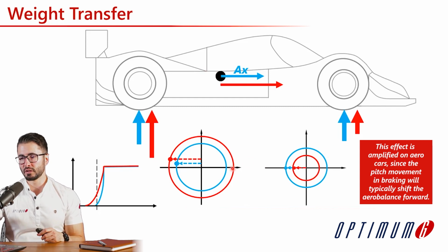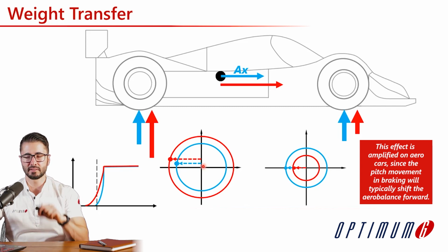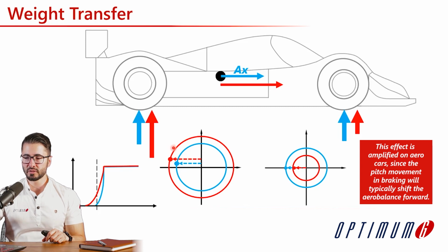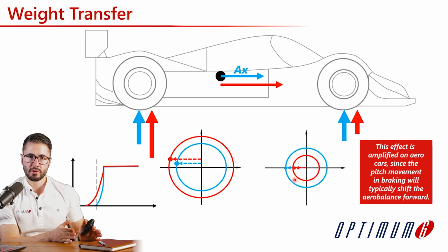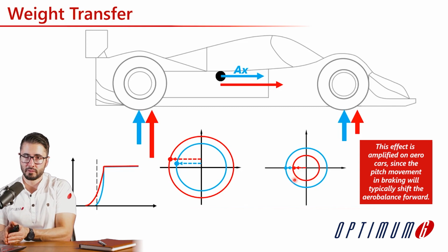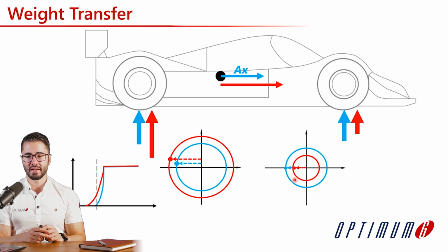So it's interesting to see that even though you are using more of the longitudinal force of the tire and slightly saturating it longitudinally, you still have higher lateral forces over here, while on the front you have lower lateral forces. If you increase the forces on the rear and decrease them on the front, you're getting a more understeering car. So here, as you apply the throttle, you're going to get more understeer, typically. So this is a corner exit scenario.